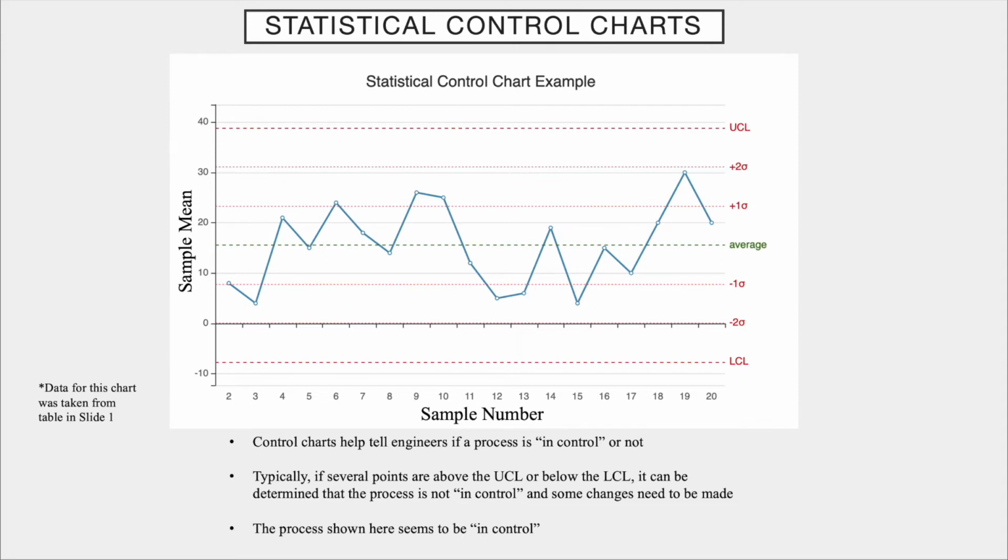In a statistical control chart, there should be an upper control limit, UCL, and a lower control limit, LCL, and a central line. The first two lines are calculated values for y on the XY control chart that mark the boundaries as to whether or not a specific test point is in control. The central line represents the perfect center of the UCL and LCL, and it also represents a population mean that is calculated to be the value that is desired, whatever that may be.